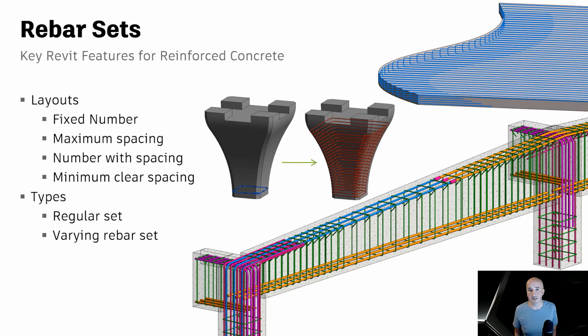When adding rebars of various shapes to concrete elements, you can define not only a rebar diameter, but also a type of layout or a rebar set. Using rebar sets speeds up the process of adding rebar by providing a quantity of identical bars.